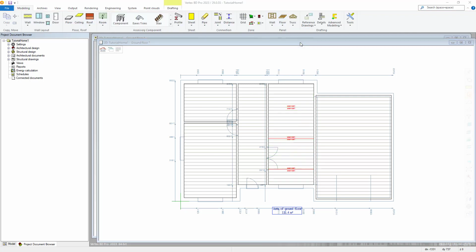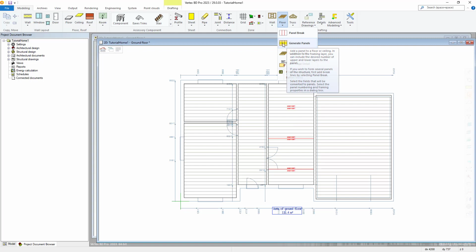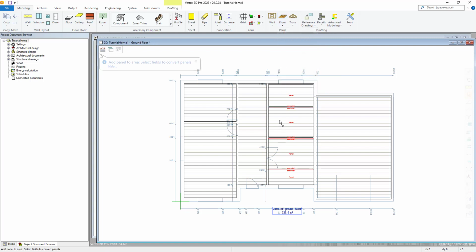After which, you can select the area you would like to add the panels to. Alternatively, first select the area and then choose the command from either the Plane Structure tab or the right-click menu. You can then select the number of layers by utilising the functions on the contextual toolbar. Select panels to be built by selecting the edge lines of the panels. You can then select all panels by pressing the Ctrl and the A key, or draw a box around the ones you wish to panelise.